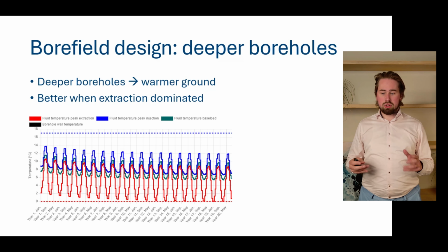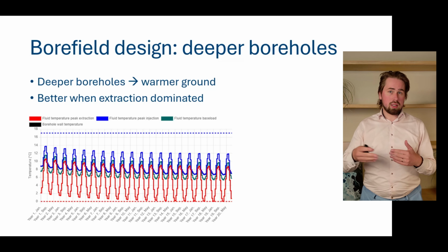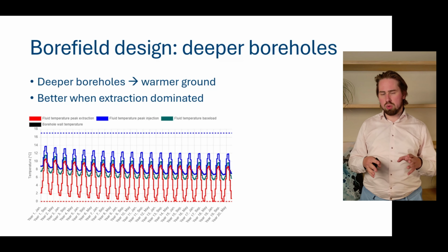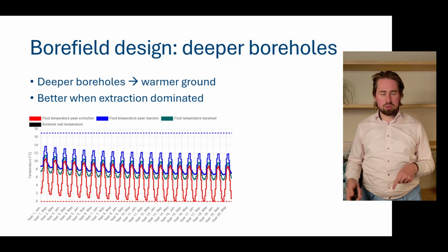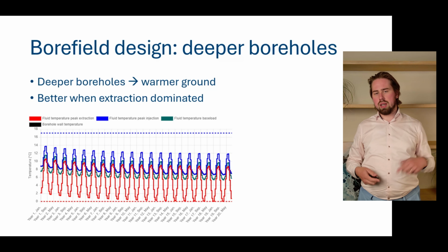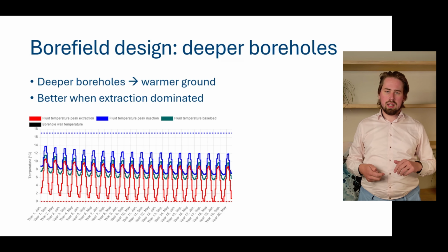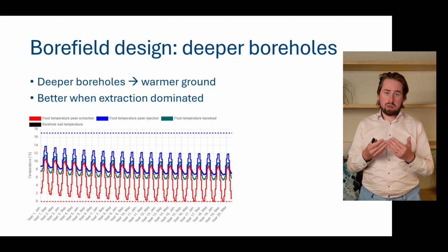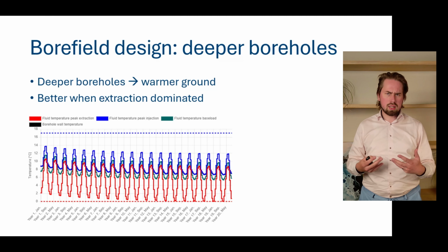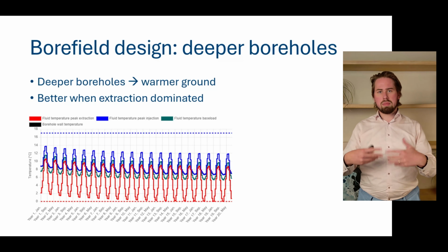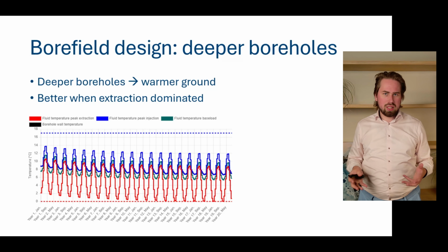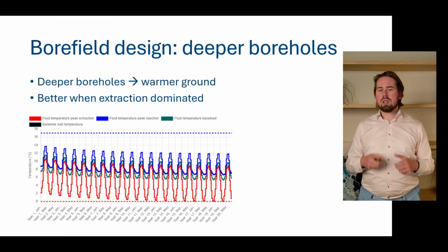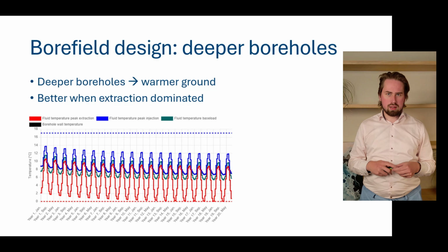Now, another advantage is if you drill deeper, perhaps you don't need as many boreholes, perhaps the same total borehole length, but not the same number of boreholes, meaning that your flow rate per borehole will increase, which is also beneficial for the heat transfer and the borehole resistance, as we discussed already in the last slides. The thing is, drilling deeper is only a solution when we are working with extraction-dominated boreholes, because when you're injection-dominated and your ground heats up year after year, well, drilling deeper is not really a solution because your ground becomes warmer and it's even harder to get your heat into the ground. So this is only a solution when we're extraction dominated.